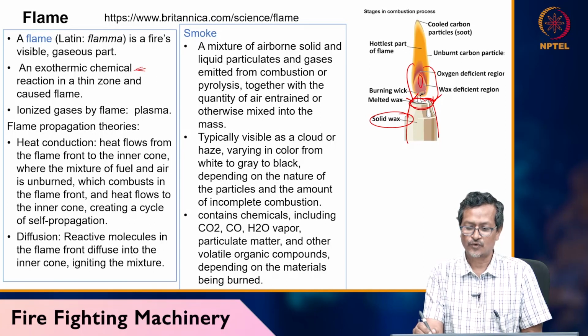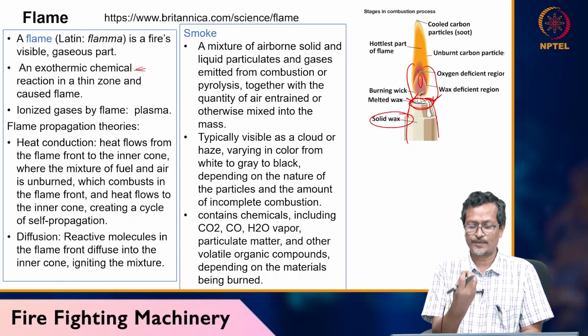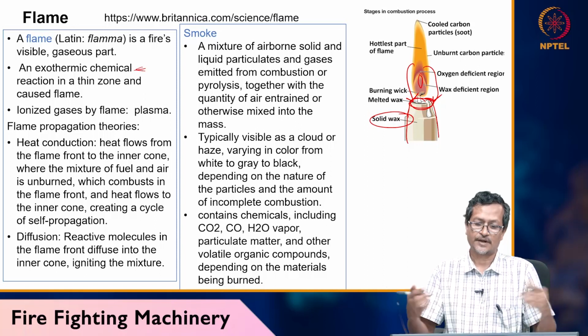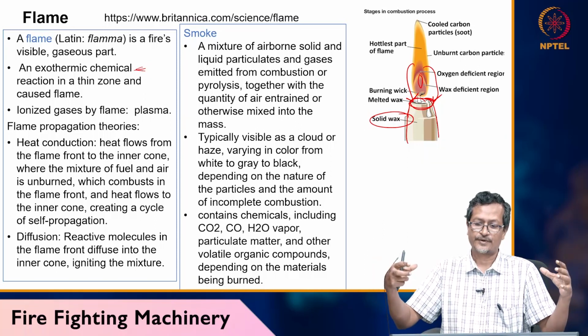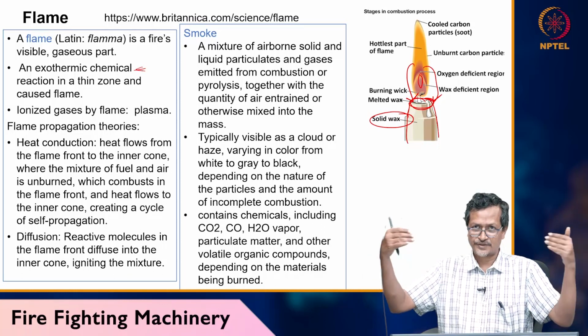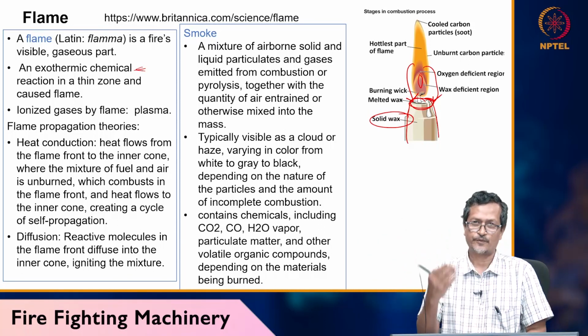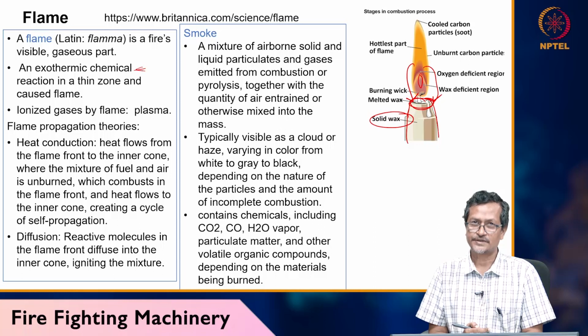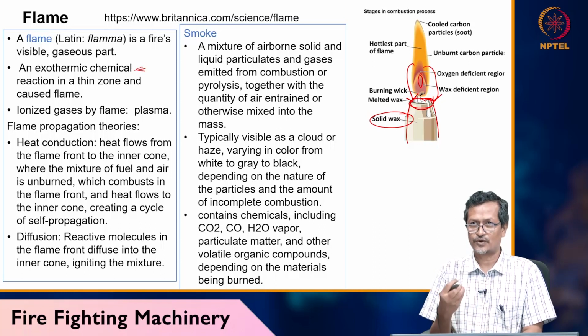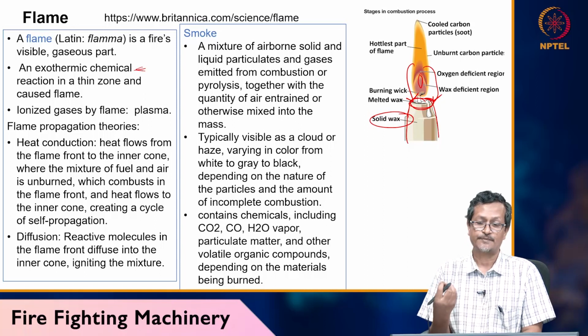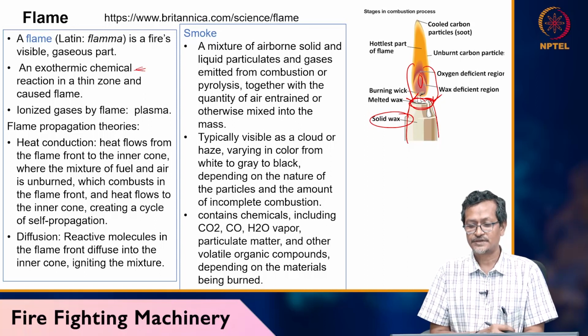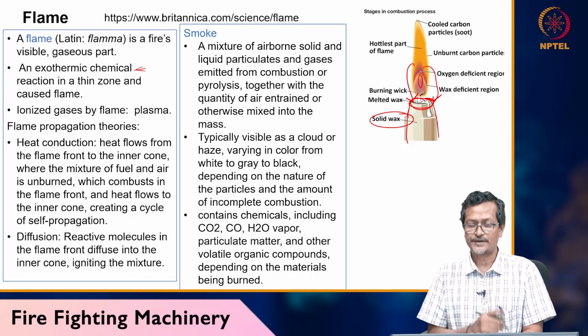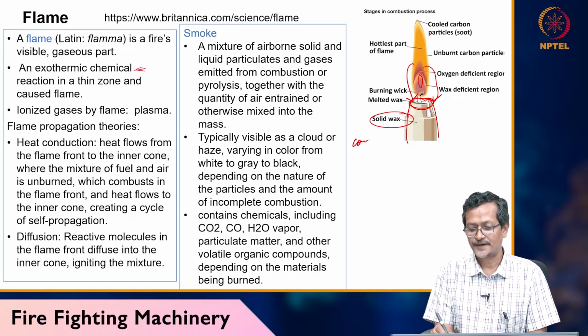At the central core, there is oxygen deficiency, so lots of fuel particles will be there, but outside oxygen will be in huge amount. So outside oxygen will be entering the center core and the reaction will be proper and it will move up. Now if the oxygen amount is lower, fuel will not burn completely, and in that case black smoke can come. If you see the gas oven at your home, you do not see a black flame because the combustion is complete. When combustion is complete, you get carbon dioxide.